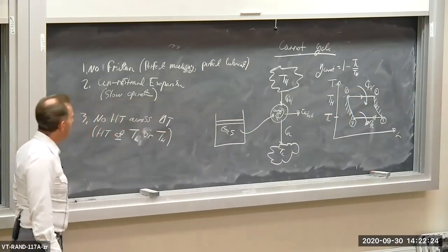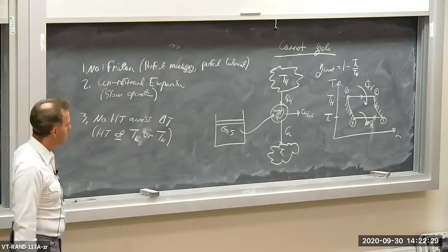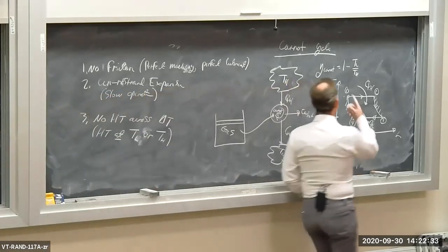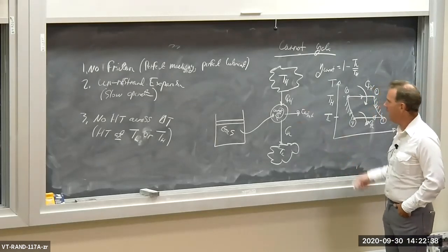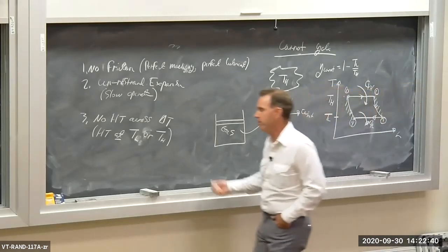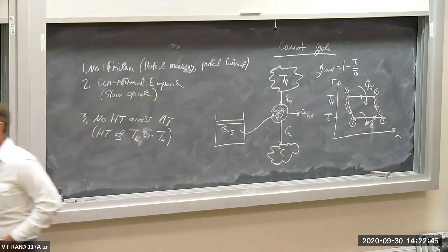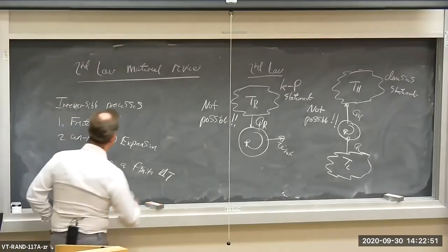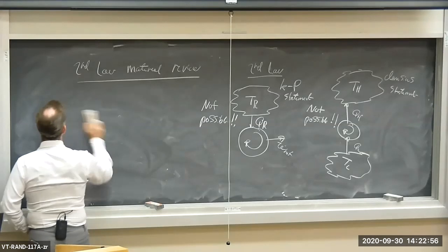Okay, so this is the Carnot cycle. This is the Carnot heat engine. There's also the Carnot refrigerator and heat pump, which work in the counterclockwise direction. Just reverse the signs on all the arrows here, and it becomes a heat pump or refrigerator. It's reversible, so there's no reason you can't do that. So after talking about developing a device, not building, but maybe conceptualizing such a device,